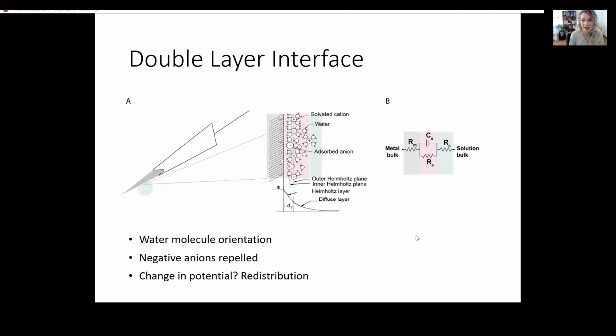So there are basically two types of electrode, and they have two different ways of detecting electrical activity created by neurons. The difference depends on the relative size of this capacitance and this resistance. This resistance is really telling us how difficult it is for a charge to directly cross this double layer. And sometimes in some types of electrodes, this resistance is very low. And these electrodes will detect activity through direct charge transfer. So charge is just allowed to cross over this double layer, and that's what we're detecting. That's how it picks up activity.